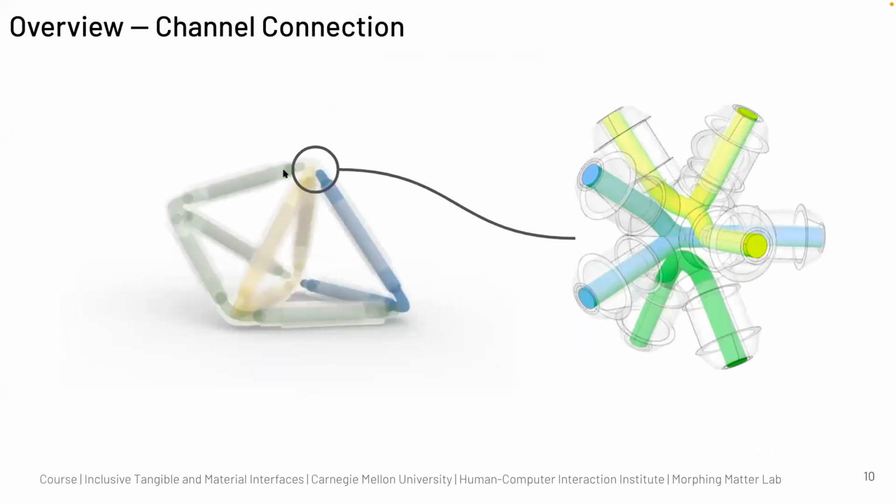The next thing is, there is a specific drawing design. As you can see, these are the channels, and different colors mean they are interconnected into different groups. You can see the channels here, only these three are connected, and these blue three are connected, and the green one is also connected. So the air will only go through a subset of the channels here. It will not go through everything. So every time you give air pressure here, only these two will get the same air pressure, but the others will not be affected.